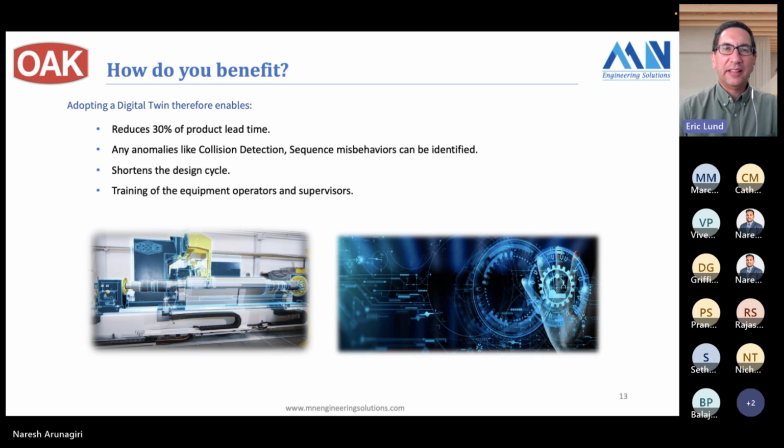And I guess I would reiterate that use that digital twin often and use it for everything. We went into this project looking at how can we reduce the software testing time and shorten that lead time. But being able to test the mechanism and also the HMI, how that operator interface works, was an excellent way of shortening the lead time that we had on our machines. And of course, rigorously testing the PLC sequences.